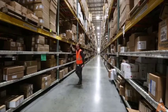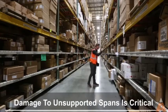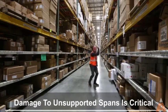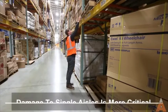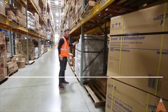Pallet rack configurations with more space between level beams, also known as the unsupported span, are also more susceptible to critical damage versus hand stack areas, as there are fewer connections to keep the system stable. Rack damage to standalone single aisles can be more dangerous for the same reason.